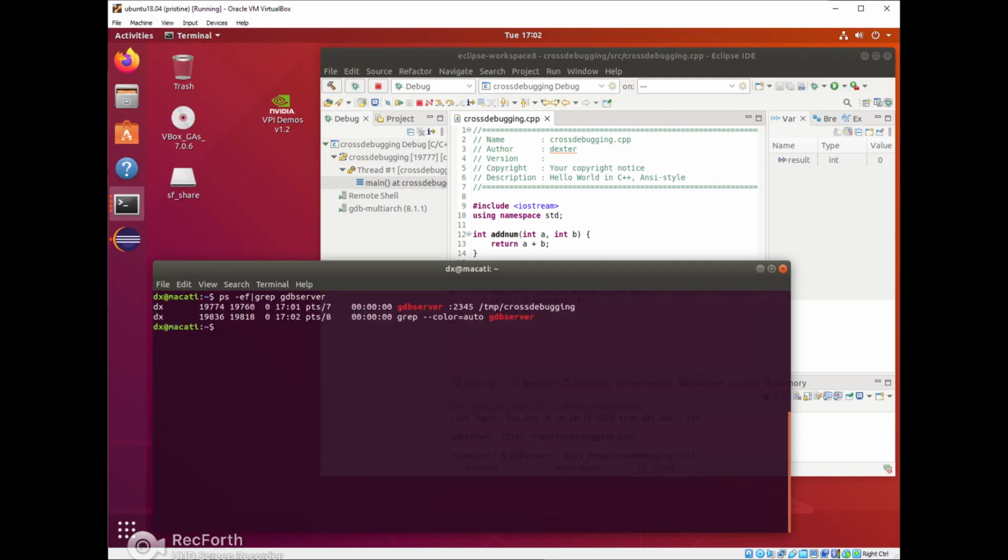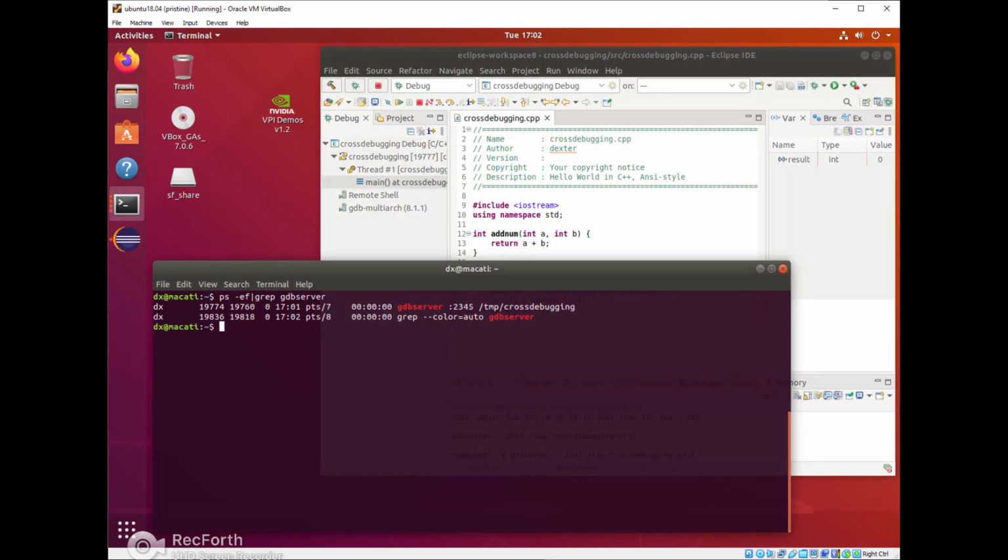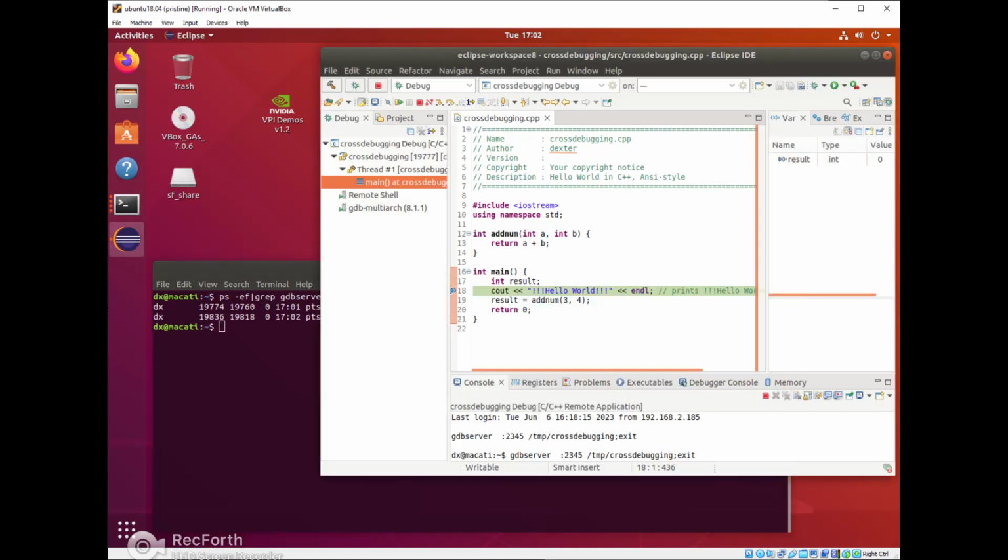If you check for running processes, GDB server, you're gonna see the same GDB server that got automatically executed by the IDE. Here, when we click debug, the IDE is doing all of this for us. Again, if you watch my other video on GDB, you will see that you have to do everything manually. So you will understand the flow.